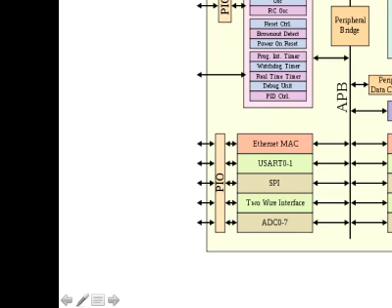This is another example of system on chip. In this case, it's based on an ARM processor core. Connected to this core is an internal bus, which is connected to different controllers, such as the interrupt controller and power management controller. Also, this chip core is connected to different peripheral interfaces, such as Ethernet, UART, SPI. Also inside this chip, it has a small amount of SRAM and flash memory, and they are controlled by this memory controller.